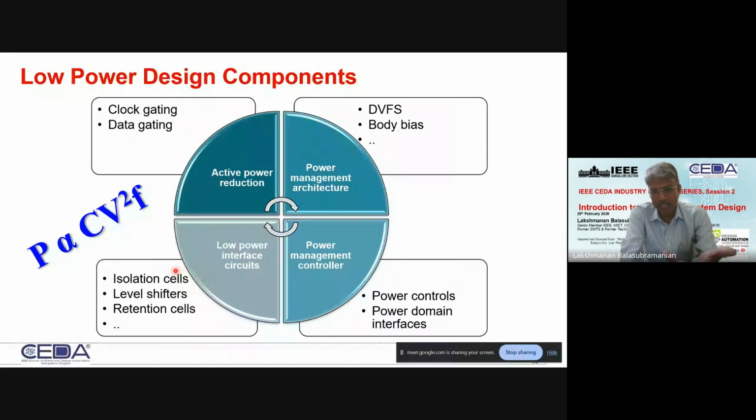And then you will have something on the power controls and power domain interfaces. This we will briefly touch upon. These are more straightforward with respect to the concept, with respect to clock gating and data gating. But the power controls and power domain interfaces, I will come to a little later. That will require functions and solutions like isolation, level shifting, and retention. I will go into the details of how and why they are required and motivate you towards that.